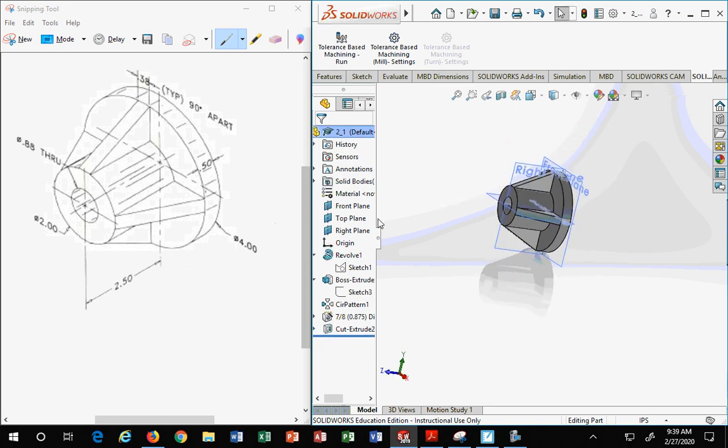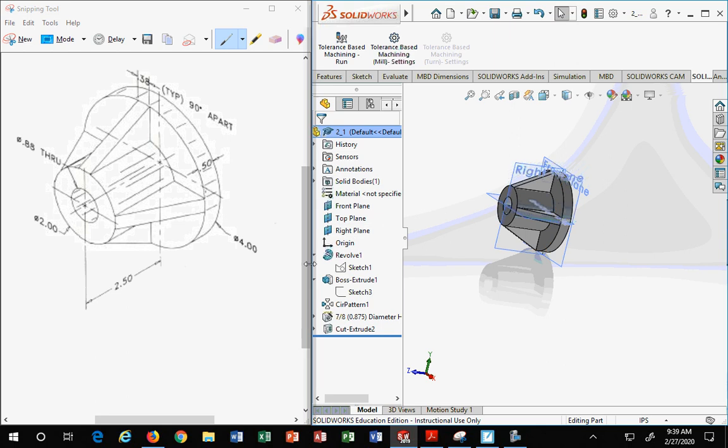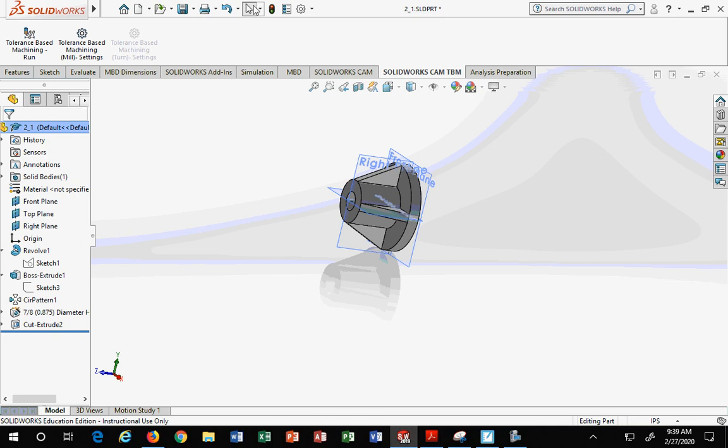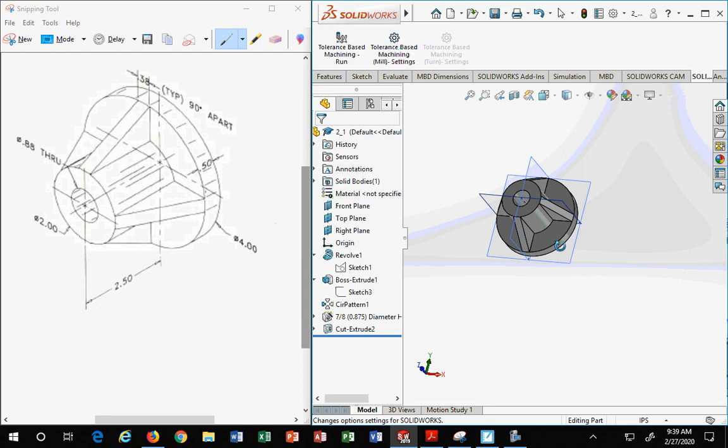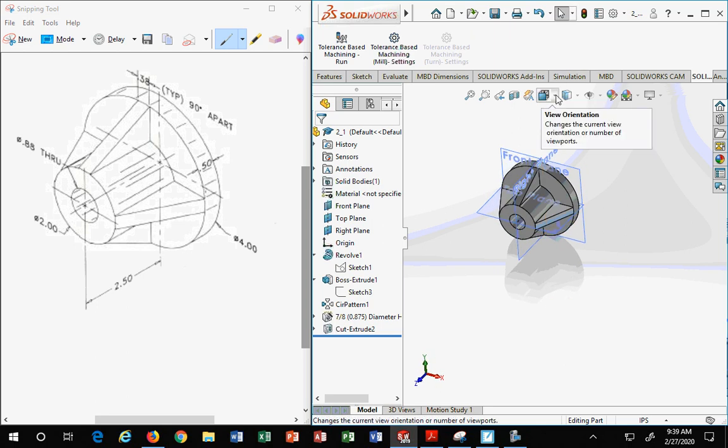There we go. Now, cool. Everything's good to go. Whenever you do a correction or a change in your model, make sure to also, I call it the traffic, looks like traffic lights in the top of your screen. Hold on, let me maximize this. See about, not top middle, but top, I don't know, by the gear area, if you look up here. It says rebuild. It looks like traffic lights. Go, no go is what that refers to. Just make sure to rebuild your part. Make sure everything's copacetic. Then we can go back to what we're here for, which is making the detailed drawing.